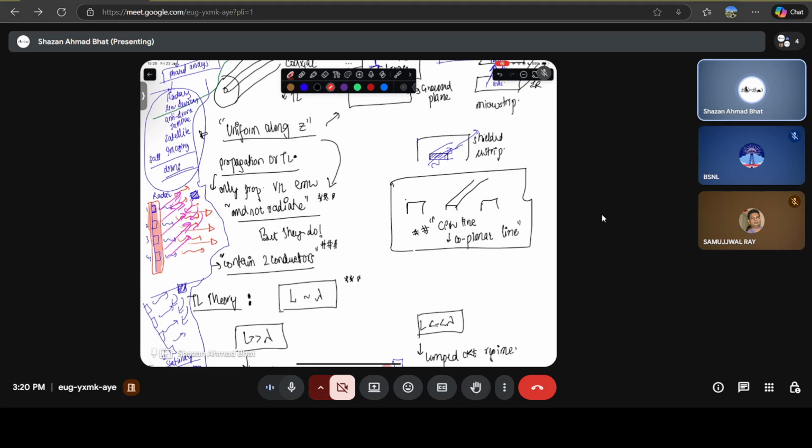Because the electric field and the magnetic fields also leak from the substrate. So if this is, for example, the strip which is carrying the electric and magnetic field, so this is carrying the electromagnetic wave. There are electric and magnetic fields which are being propagated in this direction. So this is just like fields I'm drawing, not to scale, but they are basically coming out from this particular system. So they are also the fields in space, free space.